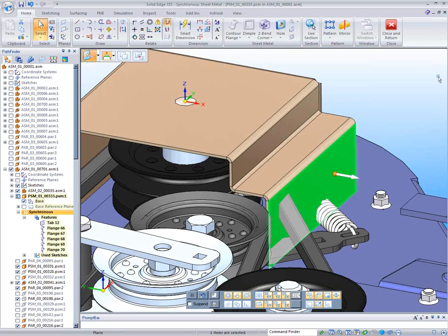In this case, this face, even though I brought it out, still interferes with everything that I've got. Now, down at the bottom of my screen are my live rules. Synchronous technology, whenever I pick a face, it analyzes that face and it says these are the live rules that apply. Things such as tangent or concentric, tangent, coplanar, those types of relationships that I have. So I'm going to turn off my coplanar and my symmetrical. In other words, I don't want anything behind here, and I don't want anything on the other side, the left-hand side of this, if you will. I only want this face.